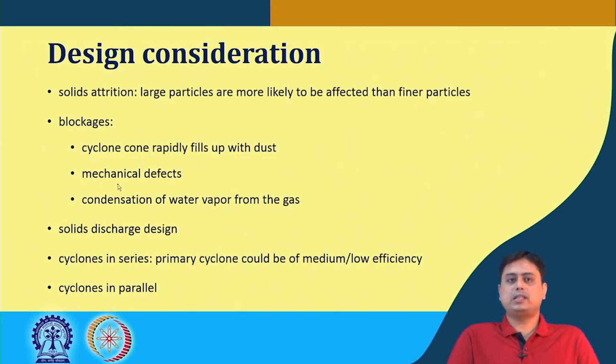So, this has to be clearly kept in mind. This blockage can happen for several reasons: rapid fill up of the solids at the conical zone, mechanical defects such as gasket blockage, or a physical property change of the feed during the operation. For example, condensation of water vapor from the gas leads to sticky material.